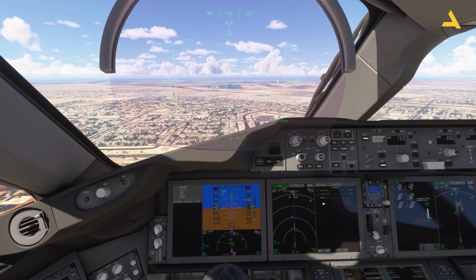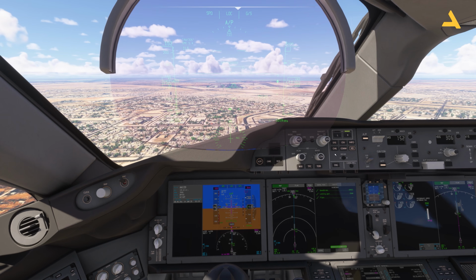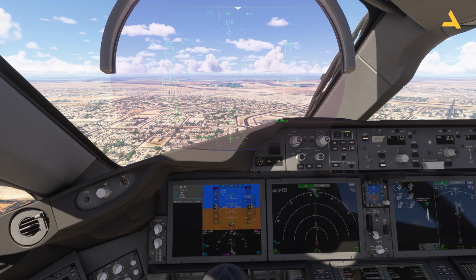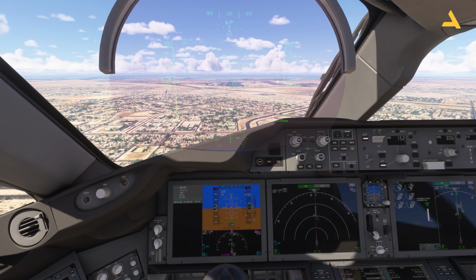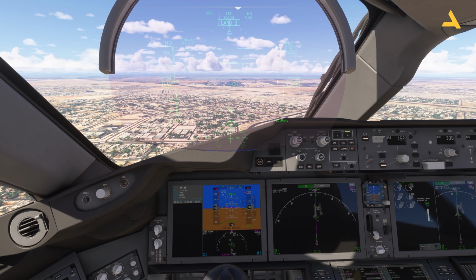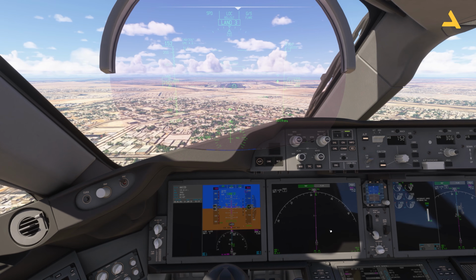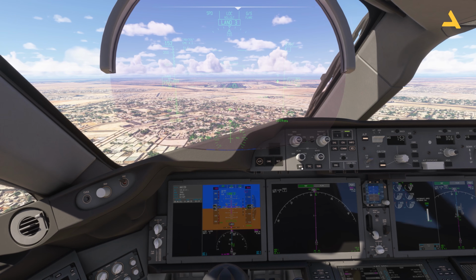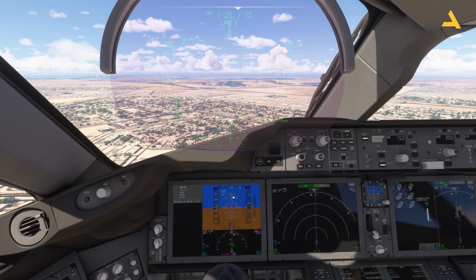That's it. And now I can extend the flaps to 30 degrees. Now I can get rid of the checklist. Not required. And I can just zoom in. At this point, you can also turn off the weather, and you can just bring this view so that after the landing you can look at the airport map. Just a suggestion, but don't do it. Line 3 is there.